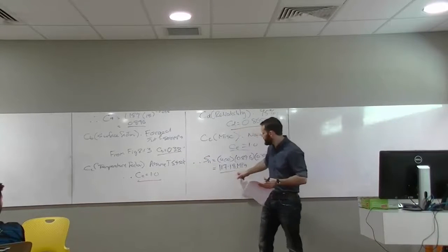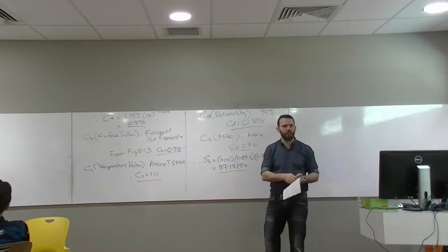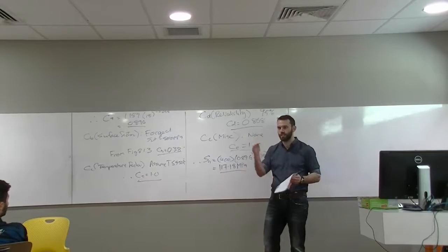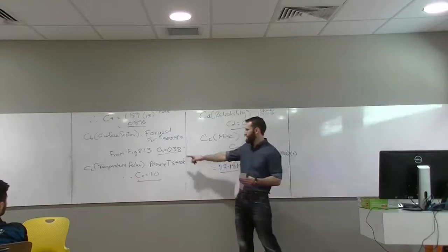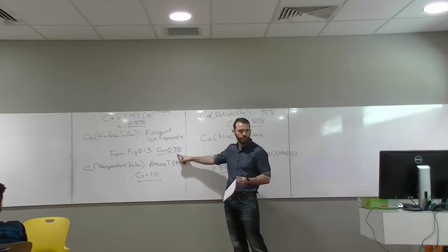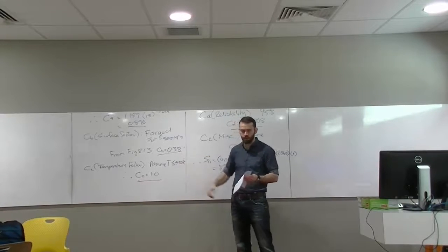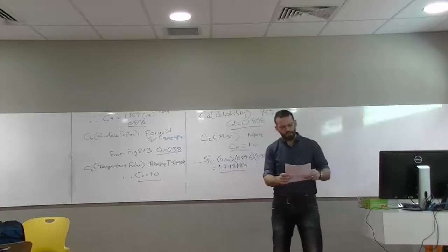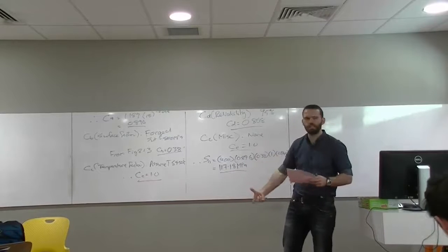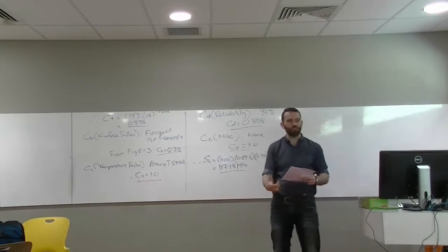If we get to the end and it doesn't carry the load that we want, we can go back to all of these factors and ask what really screwed us up. So as forged, maybe we need to machine finish something, or particularly in the critical zone, maybe we need to clean that up a bit, grind it or something. This is a real indicator of the importance of fatigue and the effect that fatigue can have on your strength.